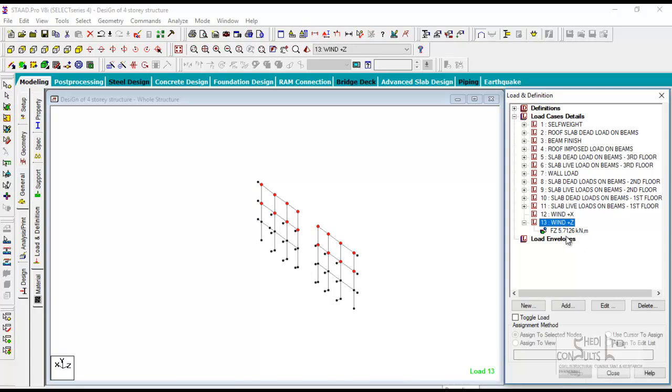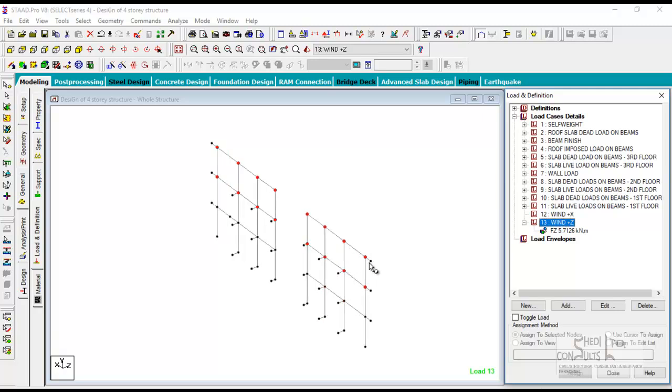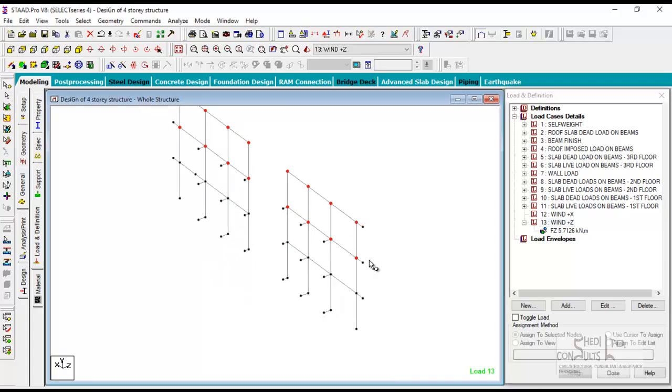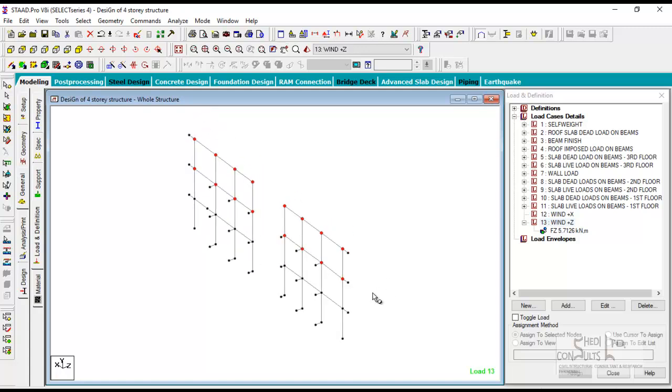So it's slightly less than what you have on the third and fourth floor, because you realize that the wind pressure varies with height, with elevation, because of the velocity profile. The velocity profile is very important in determining the intensity of wind pressures at several elevations. As the velocity profile changes with increasing elevation and you have less drag, you have increased wind pressures.